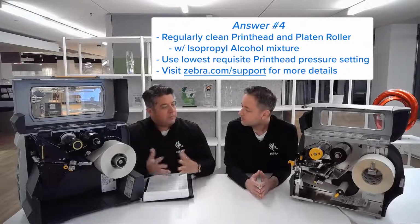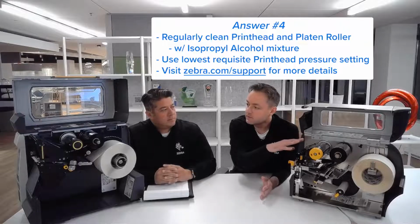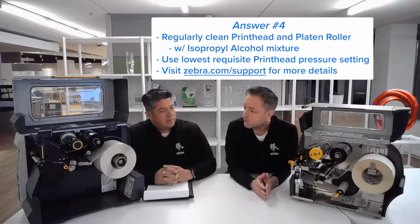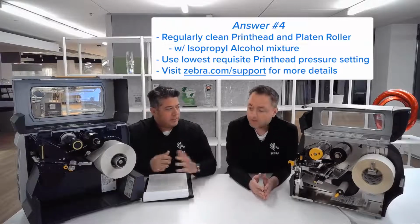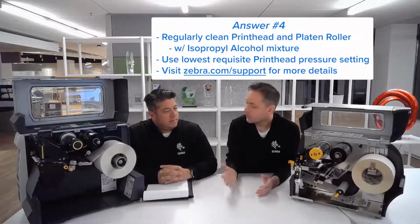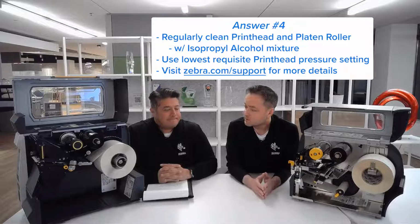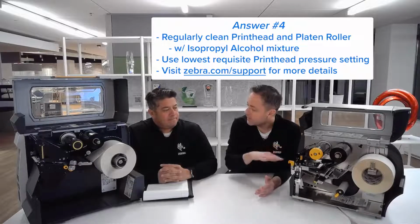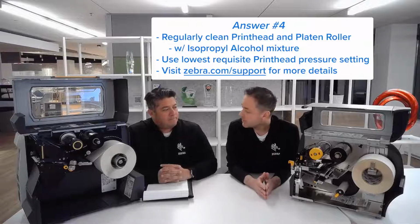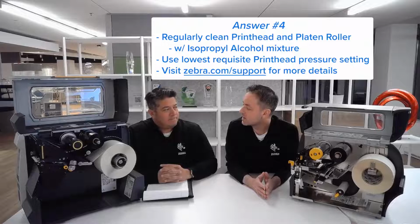How often should they be doing that then? So what we recommend is every time you change the ribbon on the printer, or if it's a direct thermal only operation, every time you change the roll of media. Okay, so the printer's down anyways, clean out the print head. Yeah, so we've got videos on our support page and our YouTube channel that show the proper cleaning procedure. There's a mixture of isopropyl alcohol that you use. You just wipe off the gunk and clean that print head. It's going to actually extend the life of it, in some cases 5-6 times longer.